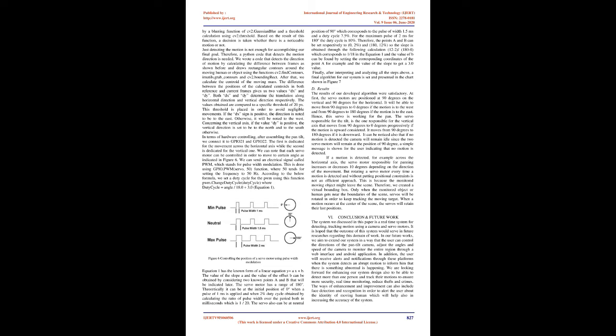As shown in Figure 4, this file exists. Figure 4: video0 file existing in the dev directory. After this, we install the fswebcam package using the following command: sudo apt-get install fswebcam. After being installed, we test its functionality by taking a sample picture through the terminal using the command shown in Figure 5. Figure 5: taking a picture using the web camera through command line.